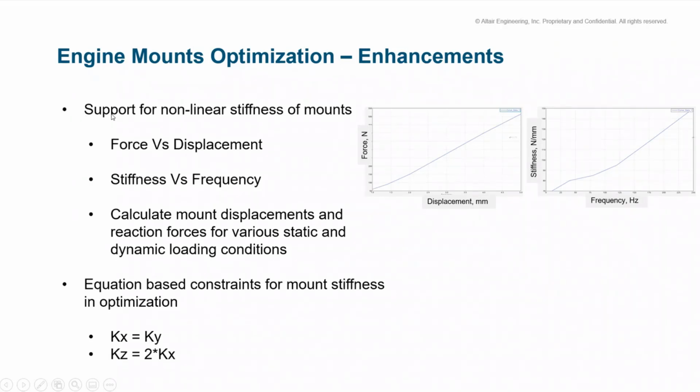And here, the idea is to support the nonlinear stiffness of the mounts, which you can get in terms of force versus displacement, or you can also get in terms of stiffness versus frequency. And for this nonlinear stiffness of the mounts, it is possible to calculate the mount displacements and reaction forces for various static and dynamic loading conditions. So this is a very big enhancement.